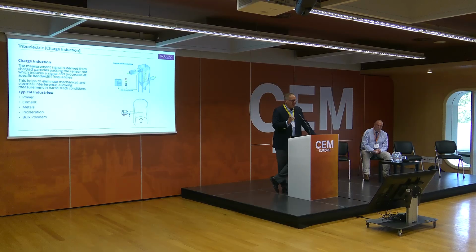Capturing the specific frequencies of actual energy from dust is very important, because by knowing that frequency, with the electronics filtration, we can filter out noise from vibration or change in velocity, and only measure or report actual charge from particulate. So the signal to noise ratio of our charge induction instrument is higher than some of the other technologies. Typical industries include power, cement, metal, incineration, and powder and bulk.